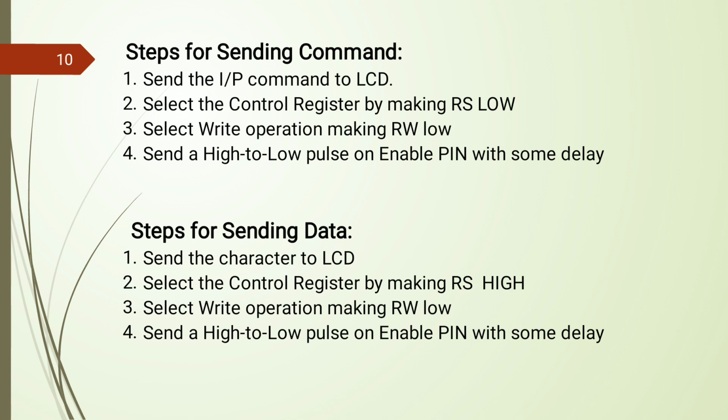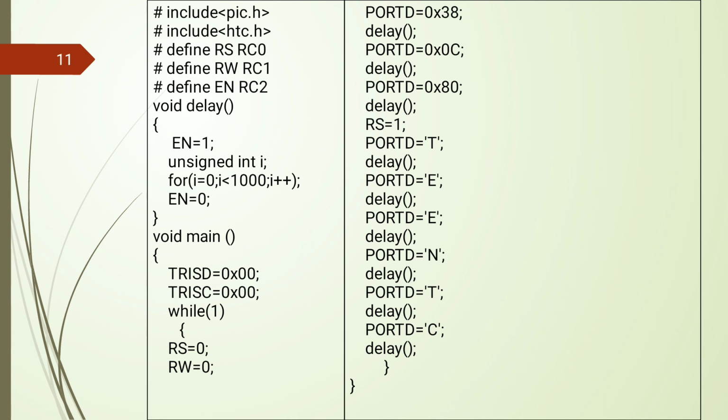So after that we discuss the code. In this code, some initial settings are done with the help of MPLAB, like source file adding, header file adding, and then we start the C program. So here pic.h, or you simply mention PIC16F877A.h, for accessing the SFRs and some registers of the PIC microcontroller.